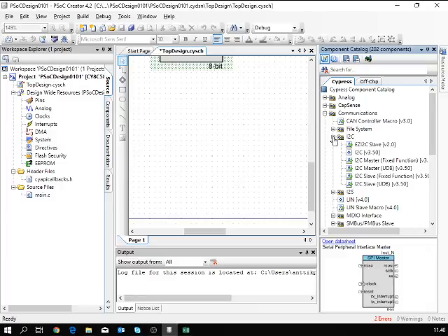So you can use this as an I2C device where an external microcontroller can read or write certain memory locations. That's probably the easiest way to connect to Raspberry Pi, since there you have the I2C. You can even write higher level language code with Python to access the I2C bus.